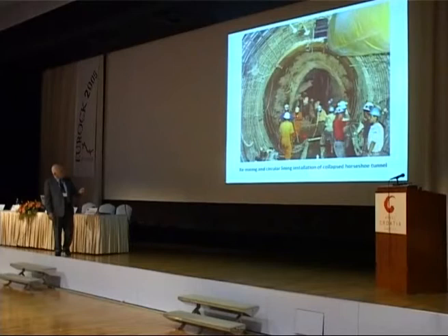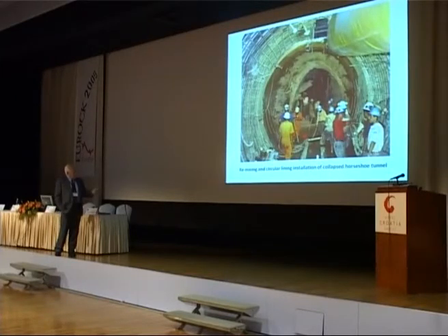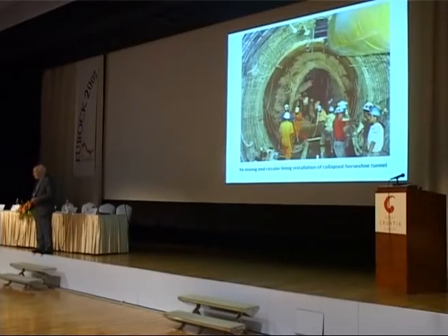That's one of those tunnels, one of the horseshoes that has collapsed almost completely and is being remined. Fortunately, the remining is pretty simple because the stresses have now been dissipated, and so you can put in a relatively light concrete lining.